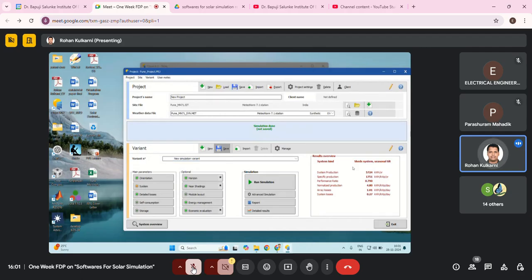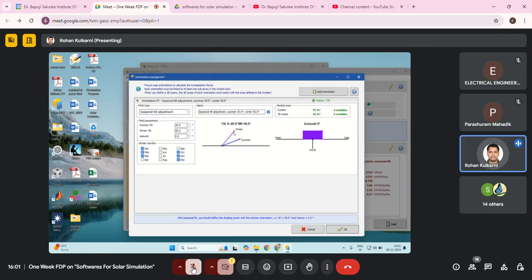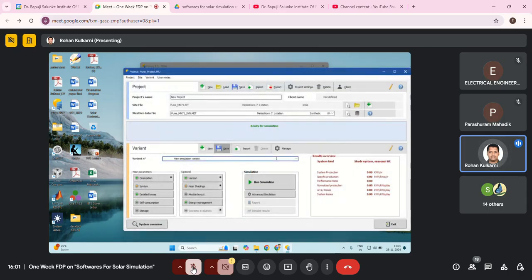Okay, here it will give you the summary. 5724, yeah, that number changed. Before, it was something like 5 thousand-something kilowatt hours per year. It has changed due to the orientation. If I change the orientation, and even if I change the angles, it will change based on that. As it is a grid connected system, we are not interested in tracking and all, but still we can always check. Yeah, I'll make another orientation.